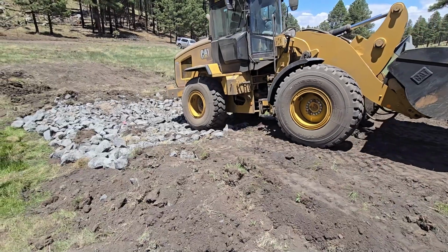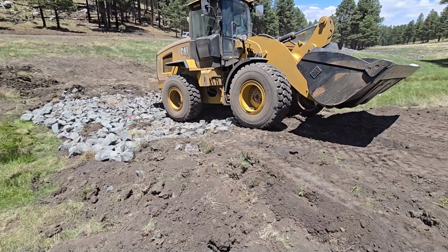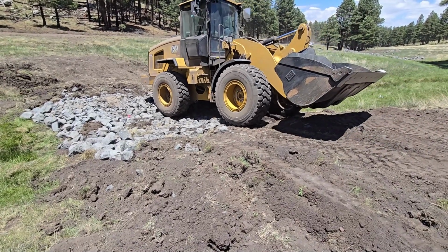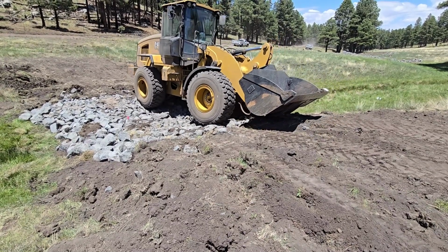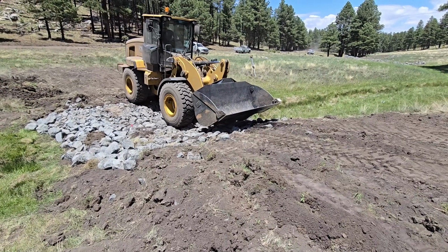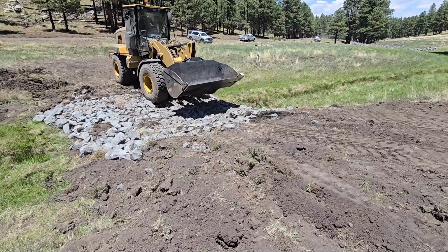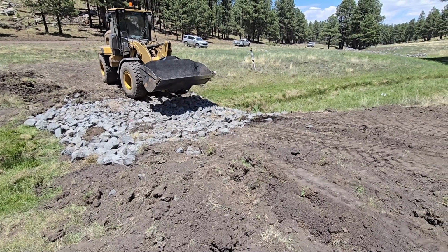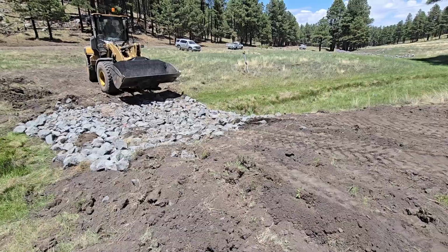Here Ethan is using the wheel loader to embed rocks in the inlet that we built for a restored wetland. I asked Ethan to use the wheel loader to drive over the rocks we placed on the higher and drier ground. The heavy weight of the machine on rubber tires is better able to push the rocks into the ground compared to using the excavator. We kept the wheel loader off the groundwater dams and the spillways where we did not want elevations lowered.